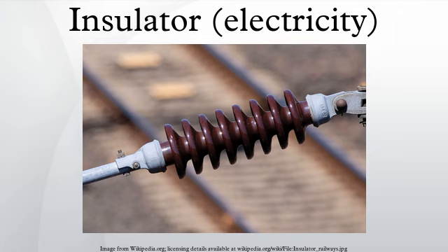High-voltage transmission lines usually use modular cap and pin insulator designs. The wires are suspended from a string of identical disc-shaped insulators that attach to each other with metal clevis pin or ball and socket links. The advantage of this design is that insulator strings with different breakdown voltages, for use with different line voltages, can be constructed by using different numbers of the basic units. Also, if one of the insulator units in the string breaks, it can be replaced without discarding the entire string.